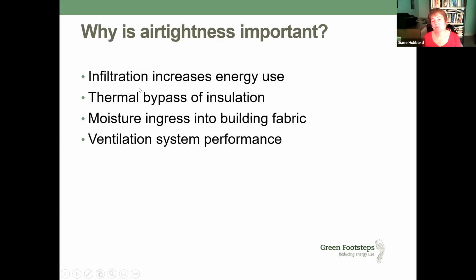The fact that with this infiltration, what happens is the air change rate in your home increases. So what you find in some buildings is they're particularly difficult to heat in cooler weather, and in windier weather, because the wind forces the air to change through the property more frequently. So your heating system physically can't keep up. So infiltration increases energy use.